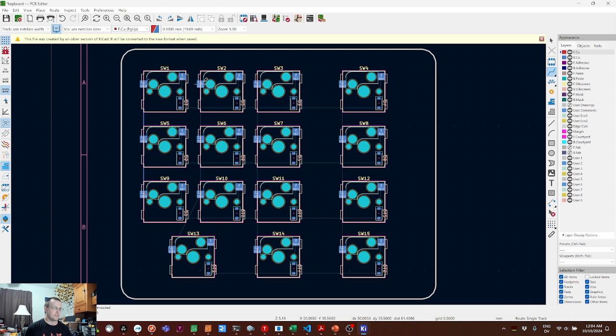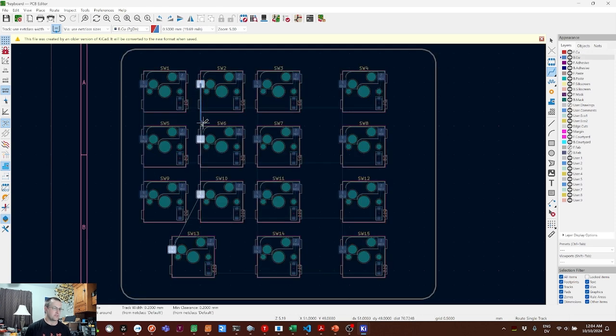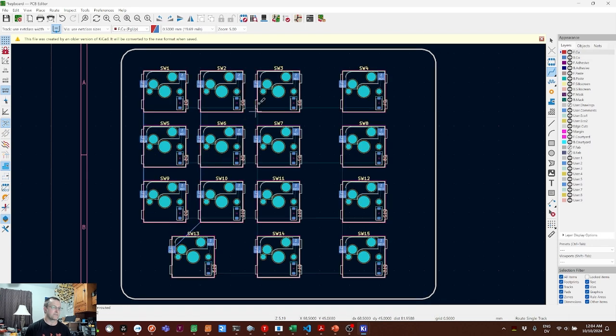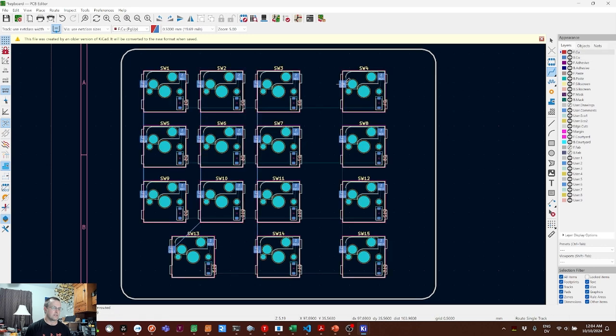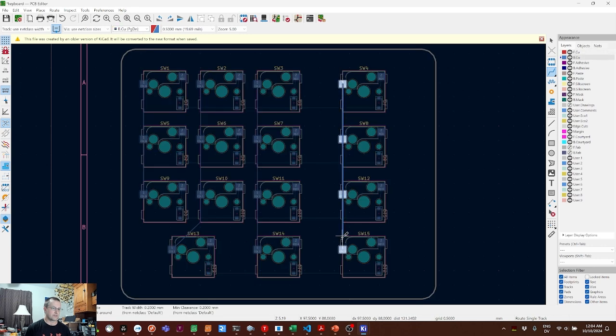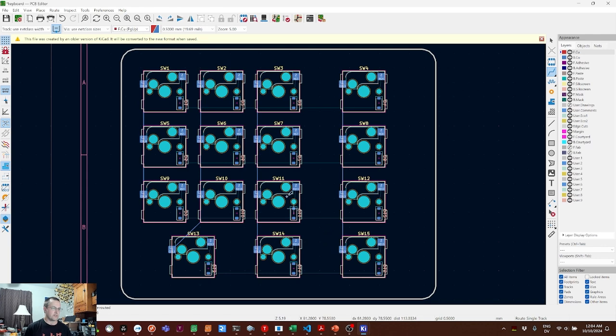We're going to do the same thing here, except we'll speed it up a little bit by dragging through this pad onto the next one, and then to the final one here. You'll notice that the trace kind of tries to follow your mouse cursor. If you move over from here, it's going to route the diagonal line around, but if you mouse over the pads that you want to connect, you can just click to route all of them at once. Column 2 is easy, they're all in a line. And column 3 finishes out the columns. Well, it's going pretty fast.